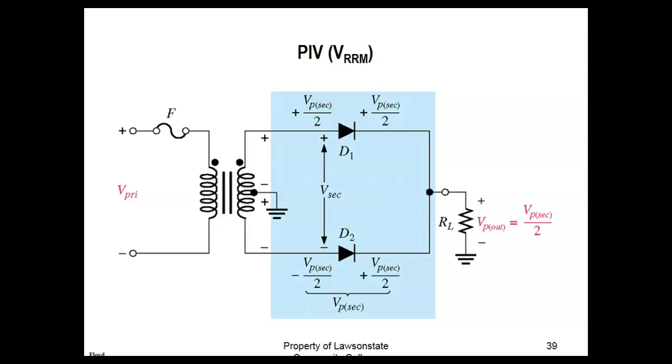Oh yeah, this talks about the PIV rating, or the VRRM, repetitive reverse maximum. This is what they call it in the data sheets that we have. This is what the textbook teaches, and what's so strange is most textbooks teach PIV, peak inverse voltage, and when you start looking for PIV in the data sheets, you can't find it, but it should be obvious from the data sheet. It's going to say the maximum reverse voltage. Most data sheets explain that out.